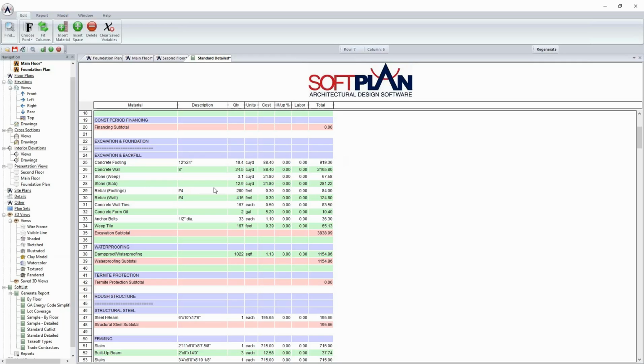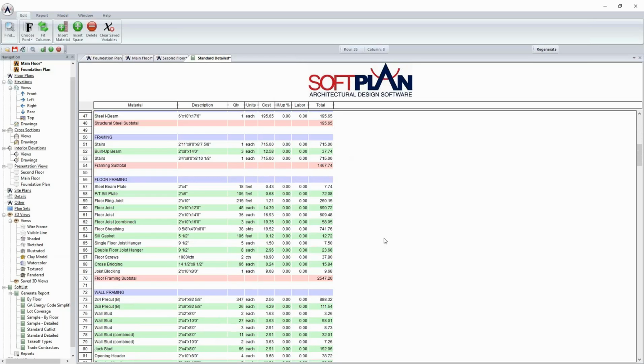In the case of the concrete slab, we may want to know, let's say, cubic yards of concrete, but again, we're going to calculate out the labor on a square footage basis. In that case, we would have a separate formula to list that out as 2 line items, because if we simply enter in labor here, it would be based on a cubic yard calculation. All right? And then you have your totals, your subtotal as it pertains to that.